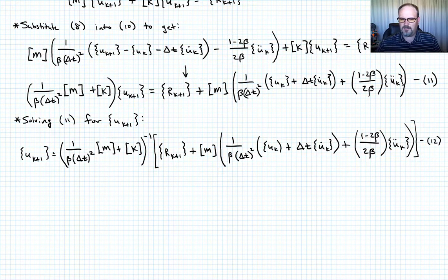So let's look at this. What can we observe here? Well, everything on the right-hand side of equation 12, except for this force vector, is related to the previous time step. So if I have a new force vector at the time step k plus 1, then the first thing I'll do is update to get the new displacement u_{k+1}.